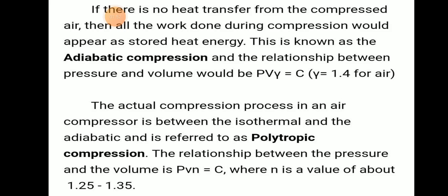If there is no heat transfer from the compressed air, then all the work done during compression would appear and be stored as heat energy. This is known as adiabatic compression. The relation between pressure and volume is found by PV^gamma equal to a constant. Gamma is equal to 1.4 for air.